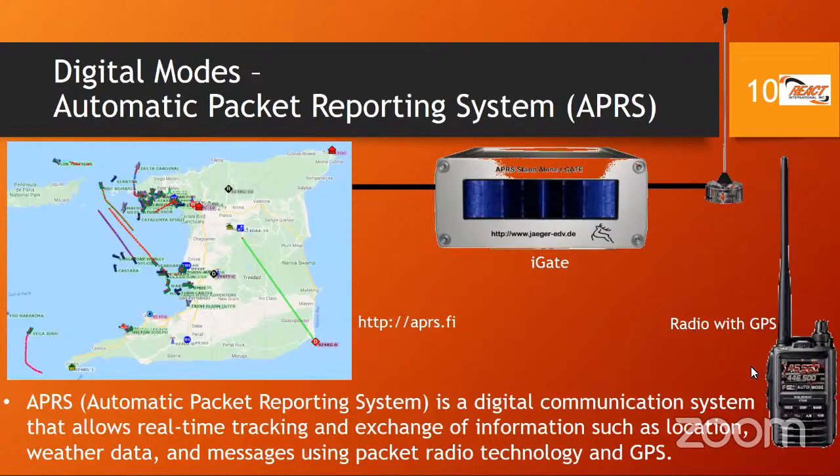So note, APRS, you use a GPS on the radio, it transmits the GPS latitude and longitude, or the location. Again, just like we have been accustomed to using GPS when we use Waze or Google Maps and we are tracking ourselves, or we are looking to see where we are on a map. Well, amateur radio operators do this with our radios. So that mode is called APRS, and it transmits packets into the air. It's received by another amateur radio operator station, maybe a base station. And this is essentially a computer, we're calling it an eye gate, and it sends that information to a website.